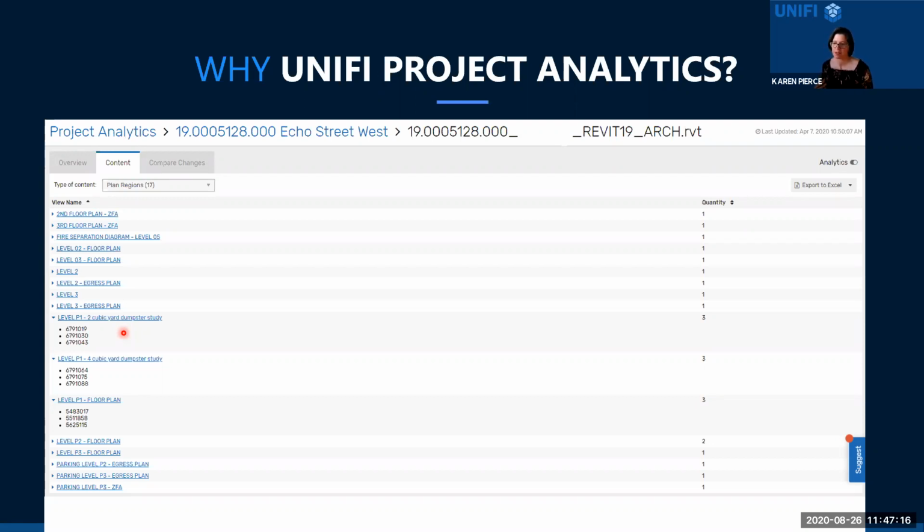So with keyboard shortcuts, we kind of talked about it in the agenda a bit, but my keyboard shortcut for keyboard shortcuts is KS. As soon as I get into KS, from there, I'm really going to be able to set those shortcuts for tips that I need all the time. Like I'm always cutting sections, for example. So the very first keyboard shortcut I set is SE for section, because those keys are right next to each other, and it's super intuitive in my mind that that's specifically what I need to do.